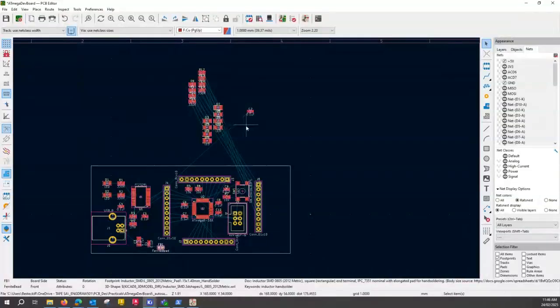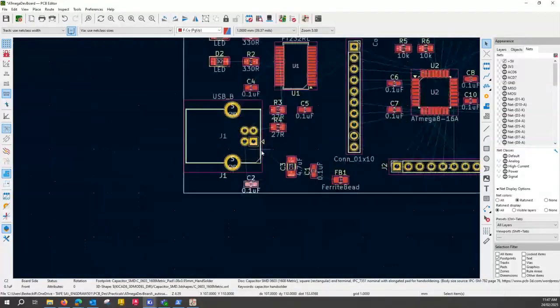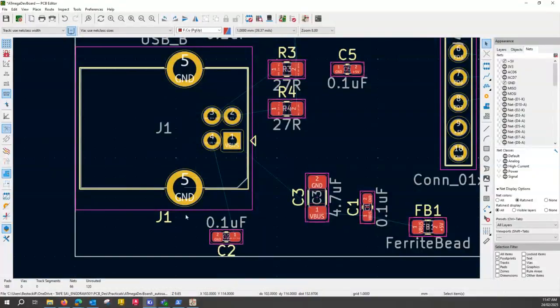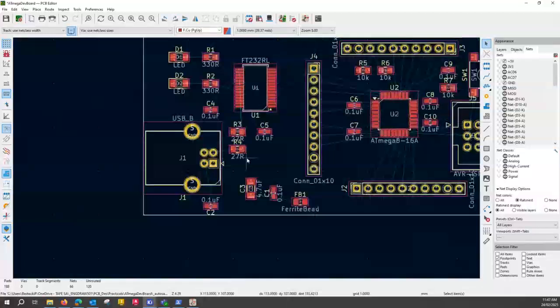And then we've got LEDs. So the rest of it is pretty much LEDs. There is this one capacitor here, C2. Where's it trying to go to? Okay, oh yeah, it's going to go in between our shield and ground coming from USB. So I'll just rotate it straight away. So it's got to be here somewhere.